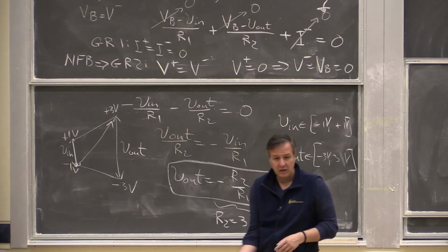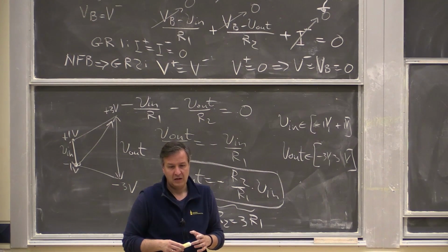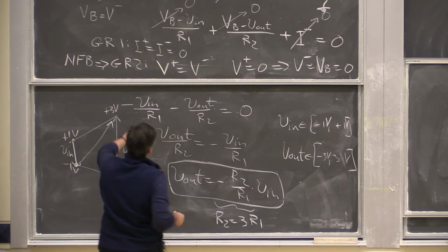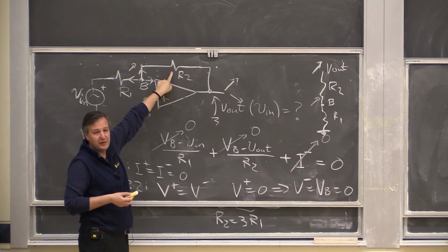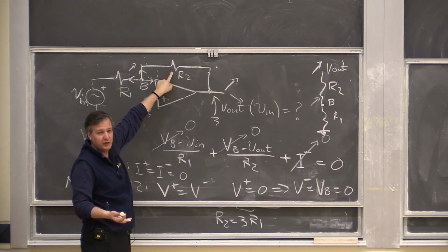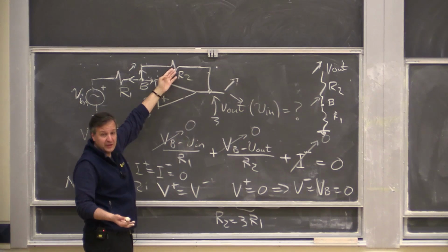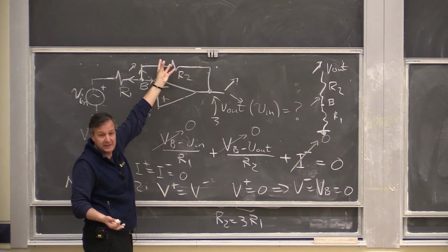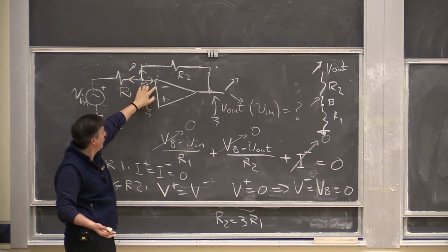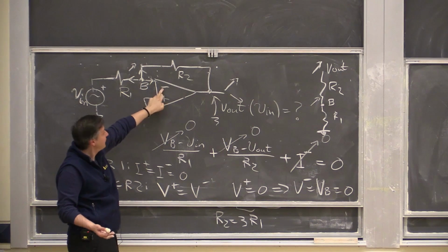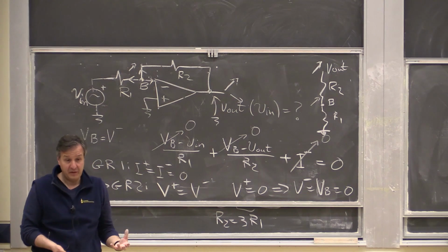You said earlier that a passive element in feedback won't change the sign of something. So I was basically saying that this is a passive element, R. Sometimes, very shortly, you'll see that we'll have C's as well. If you have just that element or a set of elements like that in the feedback path connecting output to the negative input terminal of the op-amp, that terminal has to be negative in order to retain negative feedback.